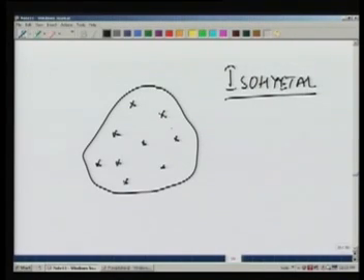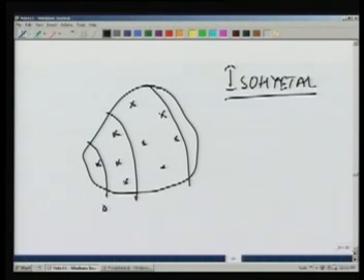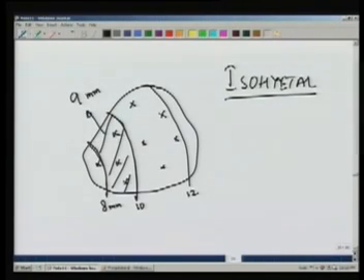So if we have the precipitation values at all these stations, we could look at those values, and using those values we could draw isohyetal lines. For example, this rain gauge, this may be 8 millimeters, 10, 12, depending on the values of these rain gauges. So all these rain gauges will have values between 8 and 10. This will have less than 8, this between 10 and 12. So we will draw these isohyets, and then we will assume that the area between two isohyets has a rainfall which is equal to the mean of the values of these two isohyets. So this area will have a rainfall of 9 millimeter,